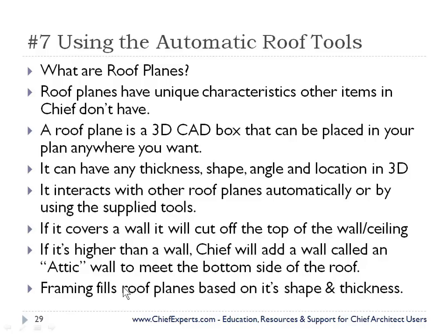And then if you do framing, framing fills roof planes based on shape and thickness of the roof box. Remember I said everything in Chief is made out of boxes? Well, if you create a container that's shaped, that's at an angle and it has a thickness and you're calling it a roof, Chief's going to fill that with other CAD boxes that look like framing. It does a really good job at that. And then you can edit that all day long and make it look exactly like you want it to be.